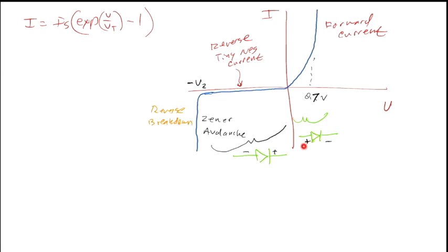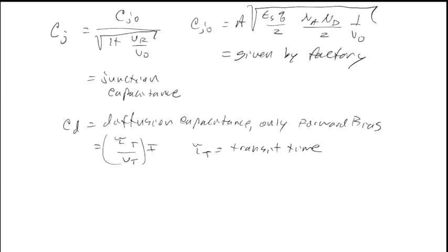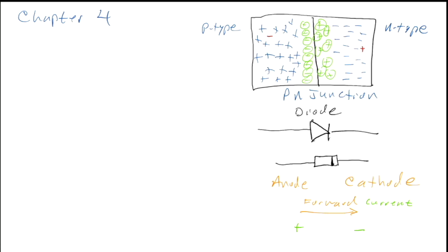And we could have minus 50 volts on the anode, and as long as we have something less than that, so if we had minus 55 on the cathode, then we would be forward biased. So the voltages could be plus or minus. It's the relative difference across that junction that controls whether it's forward or reverse biased, and whether we get a huge amount of current or not a lot of current.